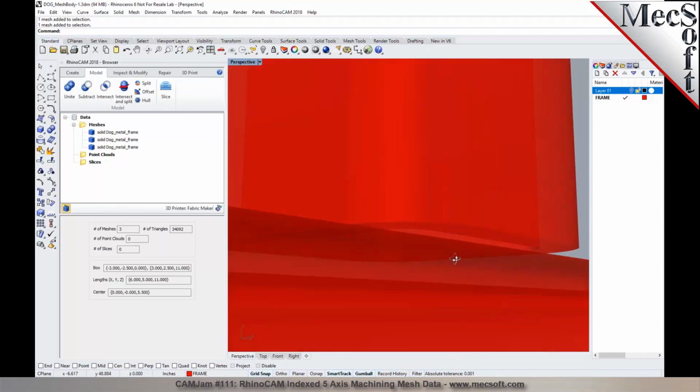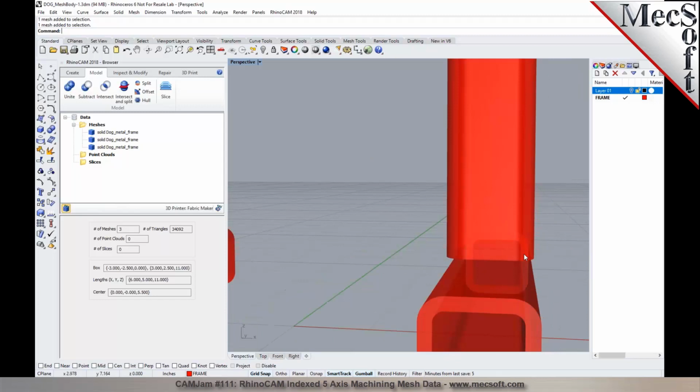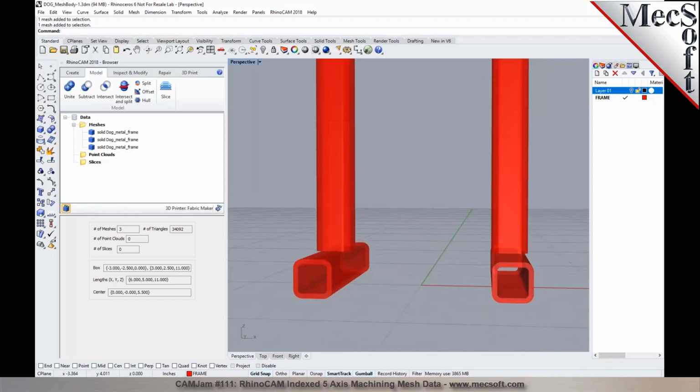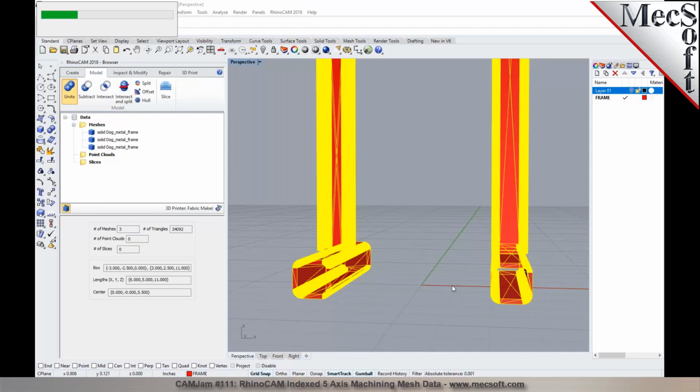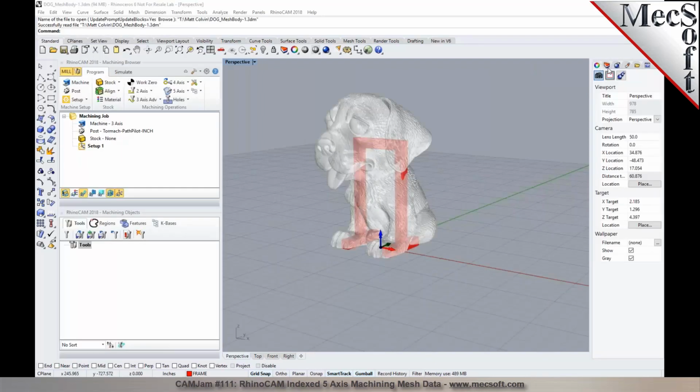You can see these frames right in here. You may want to slide them in a little bit. So there's a command called union here. I can select the objects to be unioned right there. Okay. Then I can right click on it. So the union will work if they're all closed objects. It'll union or boolean them together, if they are closed geometries.